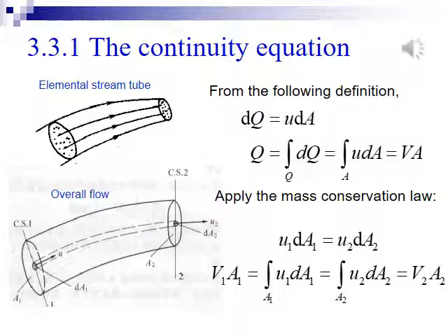Fluid continuity is a very strong restriction for flow. The speed is inversely proportional to the cross-section area, nothing to do with anything else except the flow rate. Of course, the equation doesn't give us other information such as elevations, pressures, resistances, forces, and etc. Therefore, most of the time, we need two other equations additionally to help solve flow problems.